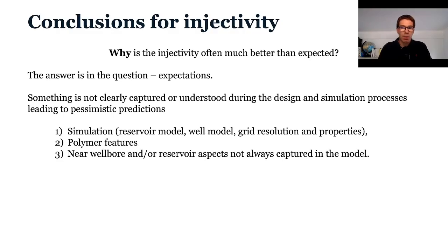And I think the most important part that encompasses all of this is the near wellbore effects. Near wellbore is basically where everything happens: change in shear rate, very high shear to low shear, perforations, fractures, shear thinning, Newtonian plateau.